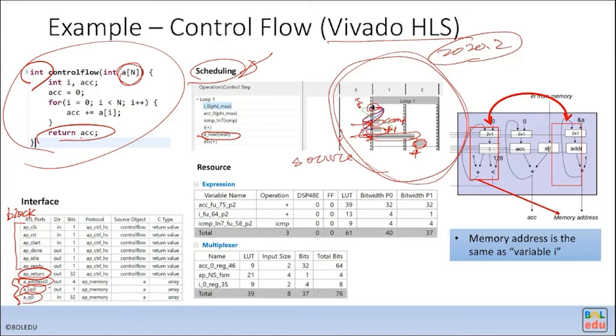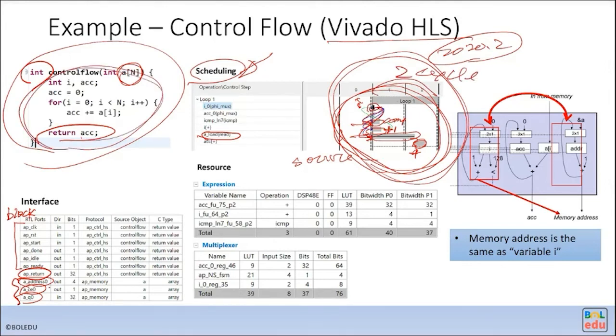So you can carefully study the data dependency here and your source code. Especially when you find the loop takes, for example, 2 cycles for the loop latency, it should be iteration latency, and you find it takes too long, then you can look at this to find the bottleneck.